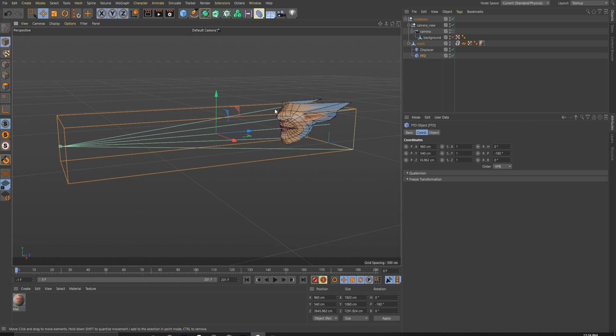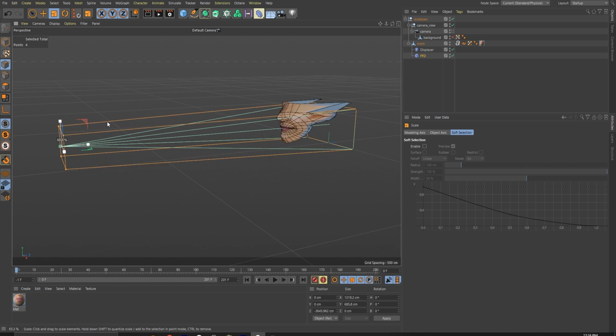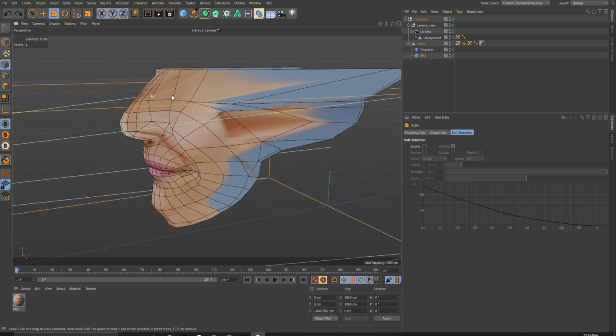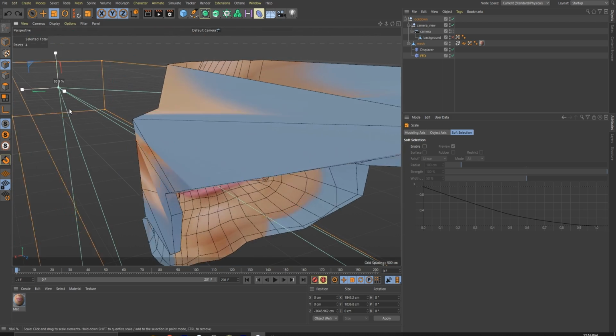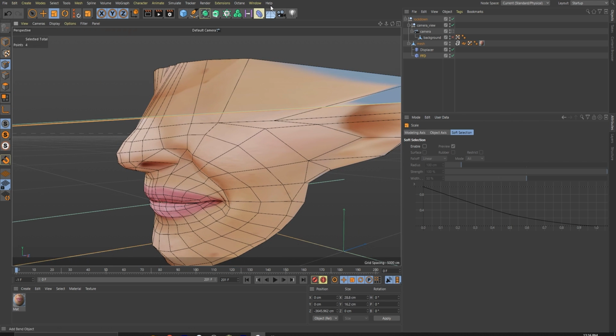So what we want is instead of this thing pushing on Z, we want these FFD points here. We'll just go into point mode and grab the 4 of these. And we'll just shrink them. And notice how that texture is coming back into alignment. So I'm going to hit undo and zoom in. And I'm going to take those and scale those down like this. But when we look, that's putting everything perfectly back into alignment.